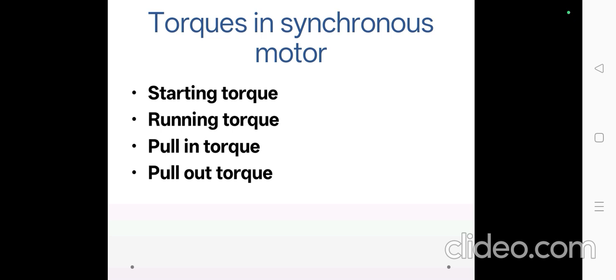Thus, the effect of change in the load on a synchronous motor connected to the infinite bus bar is summarized as follows. Irrespective of excitation, as the load increases, the load angle delta and armature current IA will increase. When the motor is normally excited, then as the load increases, the change in the current is more significant than the change in the power factor. The power factor tends to become more and more lagging as the load increases.